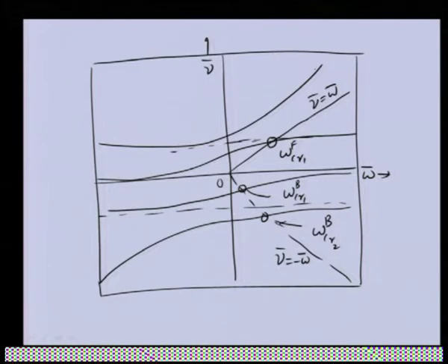And if we see the frequencies, these are the frequency lines, and at a particular omega, that means if we draw a vertical line at any position, we are getting 4 intercepts to these frequencies. So, that is because we had a 4-degree polynomial. Because of that these 4 values are coming. If we draw an identical line at negative omega, we will get 4 intercepts again, and they will be the same as on this side, because if we rotate the rotor clockwise or anti-clockwise, we should get the same whirl